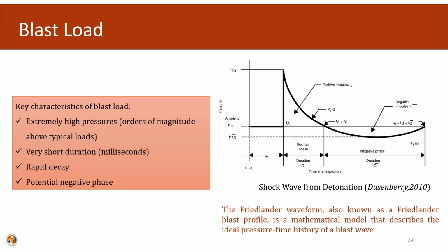It falls into a very short duration. The duration from the initiation of the explosion till the positive phase ends is very small, in terms of milliseconds. Then after that follows a rapid decay of the blast pressure. After that the negative phase comes into the picture and there is a suction in the overall system. The suction pressure might be equal to the overpressure or it might be less than the overpressure, depending upon the material used and the ground condition where the explosion occurs.